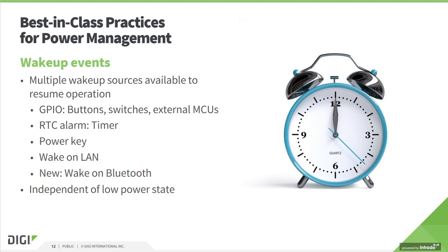In general, it is a good approach to utilize the component with the lowest power consumption in the system for power management tasks, if possible. Many developers add external, very low power microcontrollers to outsource power management. Digi adds an additional low power controller we call Microcontroller Assist, or MCA, onto the SOM, but external to the actual processing cores, which can be utilized for power management. For example, this MCA provides GPIOs, tampering pins, but also a serial port as additional wake-up source. The system can be configured to wake up on a magic word coming in on the serial interface of this MCA.